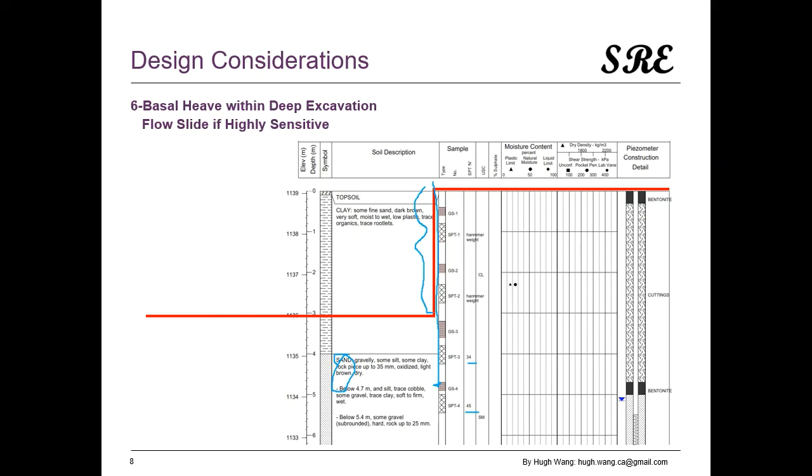Otherwise, if you leave your shoring just over here or very short, or just insert it into the sand a very short distance, then potentially you can get a kicking of the toe. So it should be inserted in the sand a few meters.